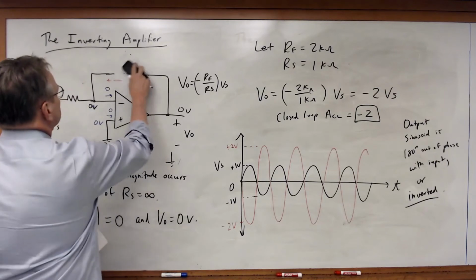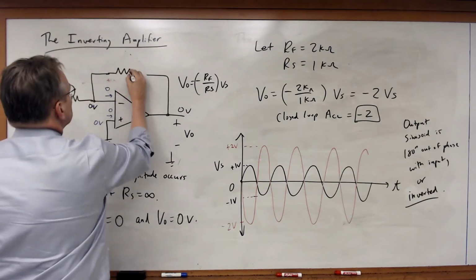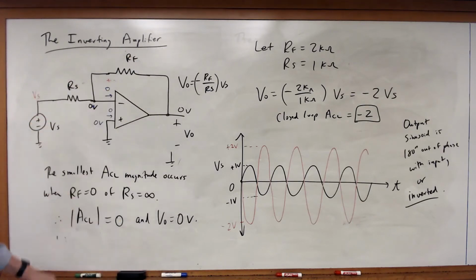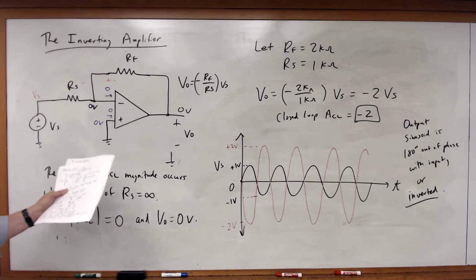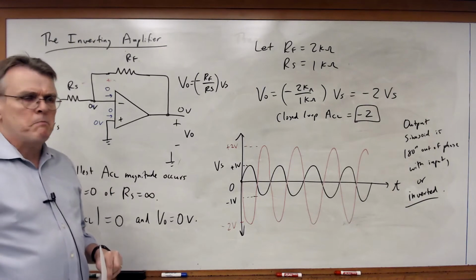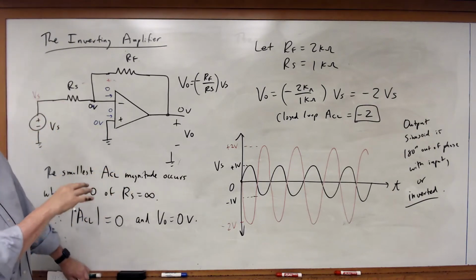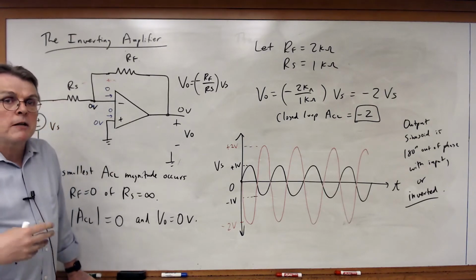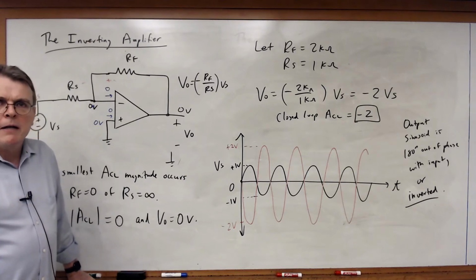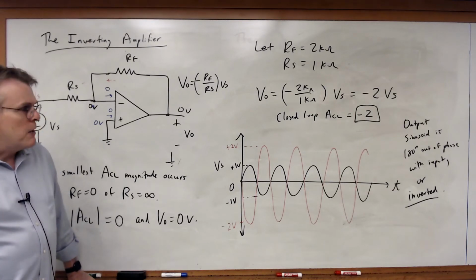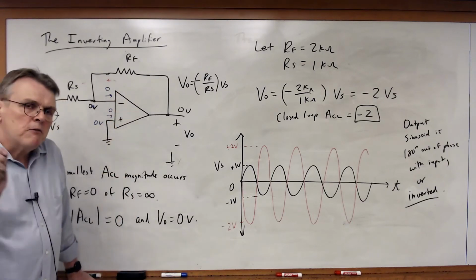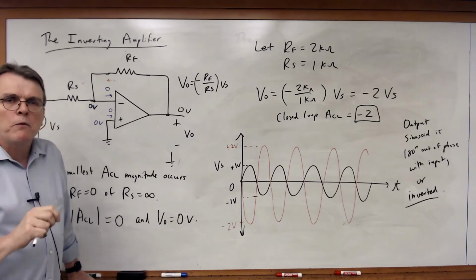Now, having looked at this amplifier circuit, I want to look at this from a totally different way. So here is, once again, our inverting amplifier circuit. Now, you guys hopefully are following the whole idea behind the 3 rules of op-amp analysis, but I want to show you an example that illustrates that really the 3 rules are nothing magical, they're nothing new. They are actually nothing more than the regular nodal analysis techniques we already understand. So I'm going to reanalyze this circuit, and instead of this being an op-amp, I'm going to replace that op-amp with a dependent voltage source.